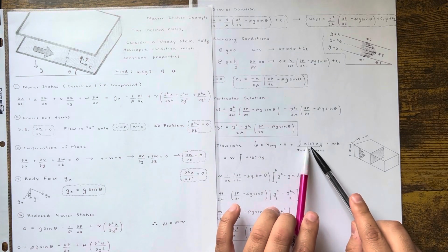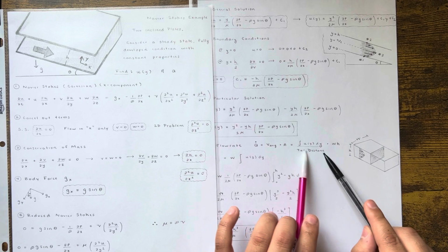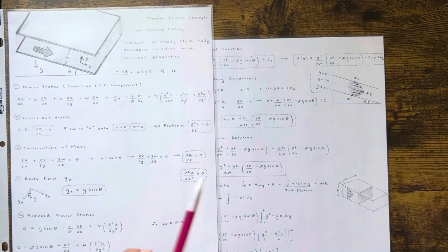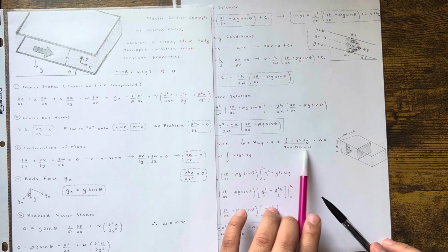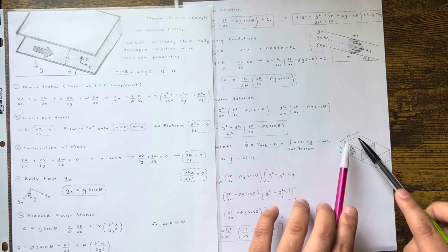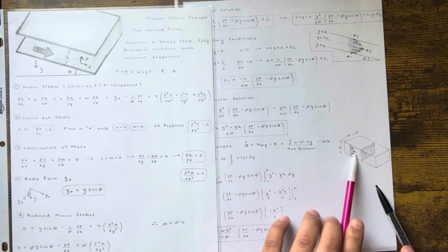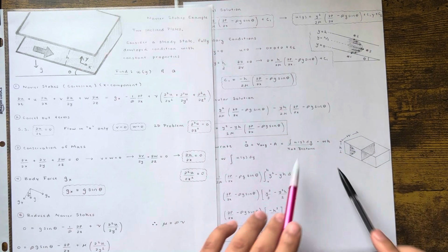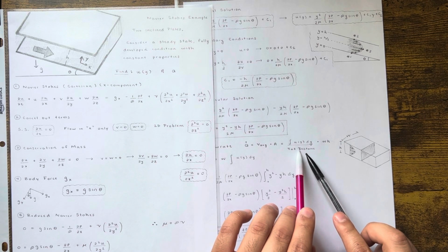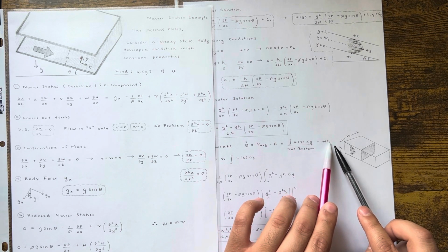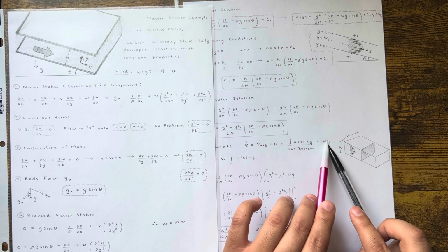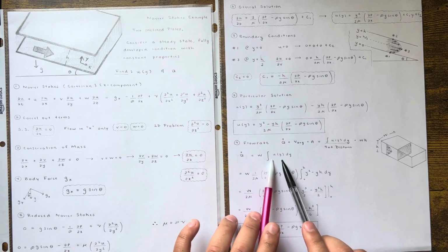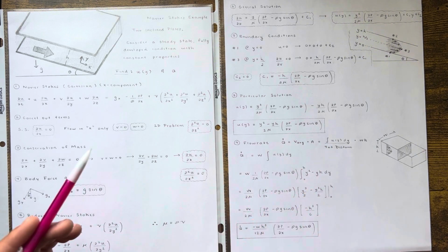So that's what I do here. I take the integral with respect to y, and you divide it by your total distance. In this case, that distance is h, 0 to h, right? So this divided by h, and then times area, width times height. So this is what we're looking at here. So this h, total distance, is going to cancel with that h. So at the end of the day, you're just going to multiply by width. So that's what I have here. Q dot is equal to w times the integral of velocity.